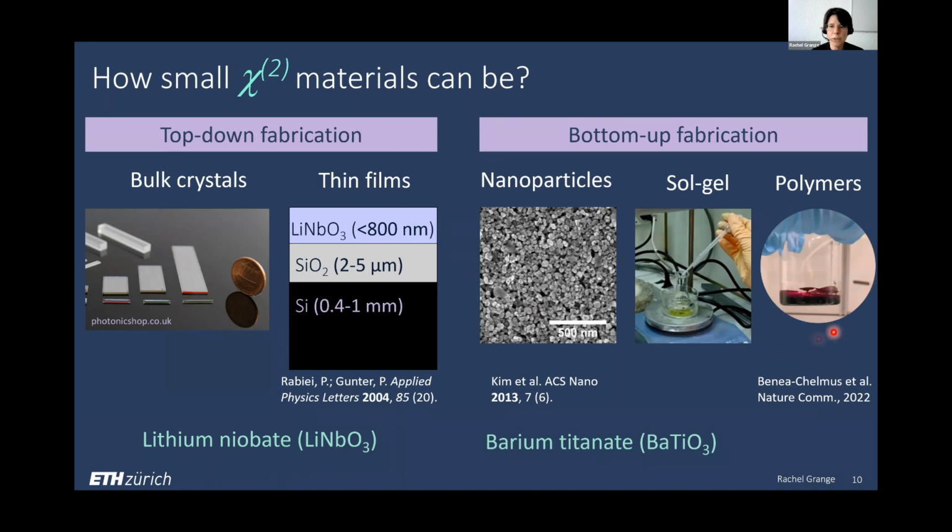And there is also interesting current work on electro-optic polymers that have much higher tensor components than lithium niobate, for instance. It could be the component I was showing you before in the tensor, up to 1000 picometer per volt, which is super interesting for efficient electro-optic modulation.